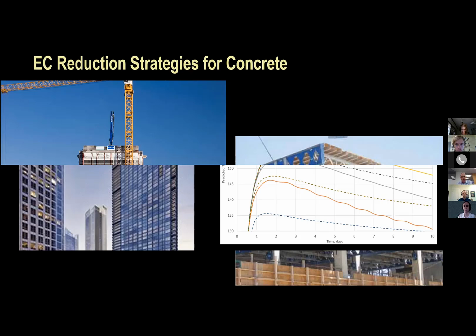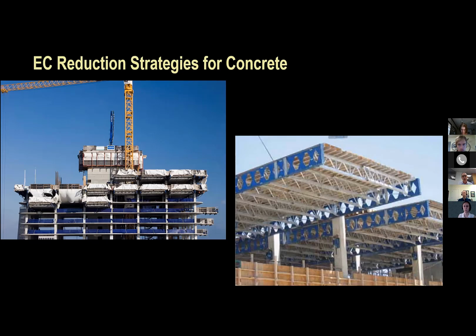And so think for a moment, just compare what happened on this project where they used column hung flying table forms, which allowed the slabs to stay fully supported for 3 full days, 72 hours before the shoring was ever stripped. And the reshore load never came onto the slabs because it all went directly onto the columns. Compare that to what would typically happen today. In fact, how we're building West 8th, which is a typical 3-day per floor cycle. It means stripping horizontal formwork at 24 hours, stressing a PT deck probably at about 48 hours, and then reshore loading kind of in that 48 to 72 hour range that is going to load the slabs up when they're still green concrete with the heaviest loads that they're probably ever going to see in their entire life.